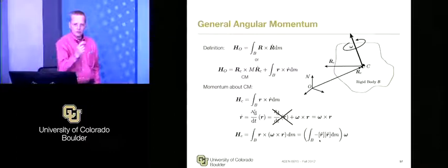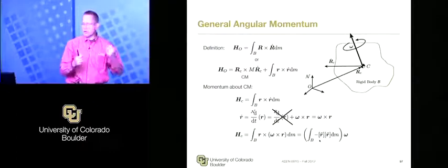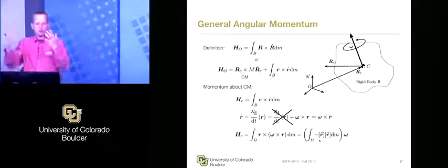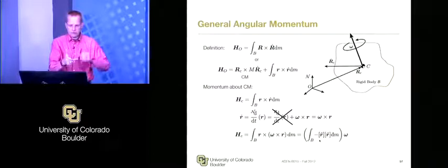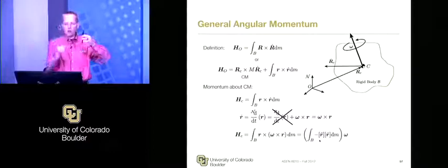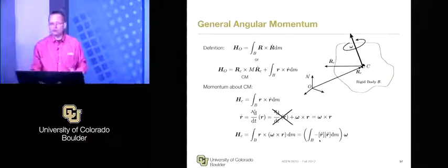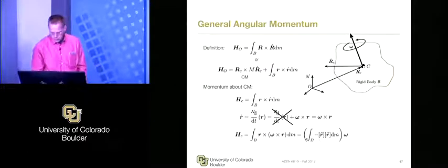So I have to pick R components with respect to B1, 2, 3, or E1, 2, 3, and then you will have B frame components or E frame components of the inertias, right? Once you pick a 1, 2, 3 axis, or you pick different 1, 2, 3 axes, you're obviously going to get different moments, different inertias about those axes. It's still the same body.